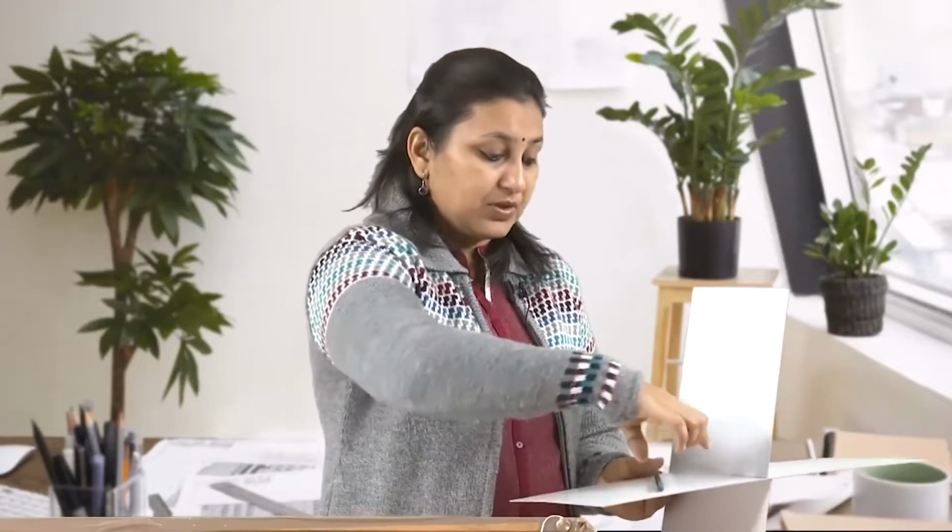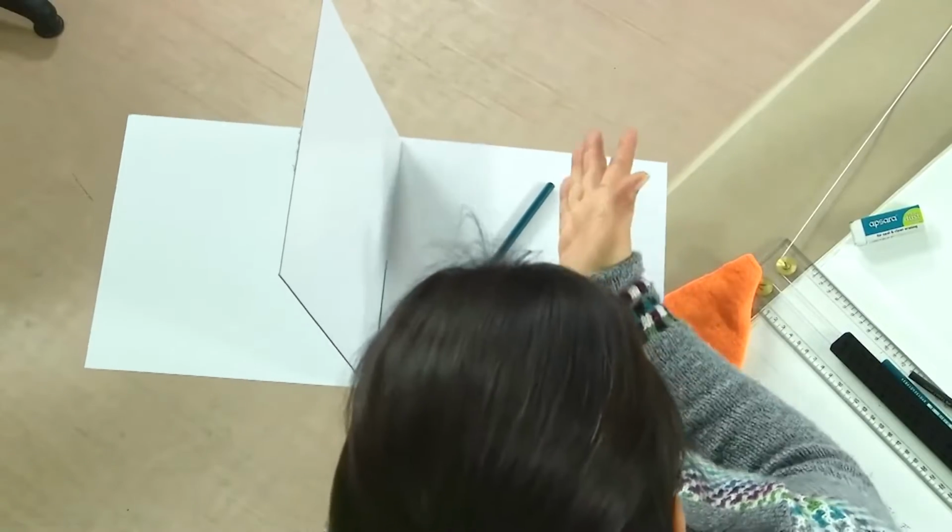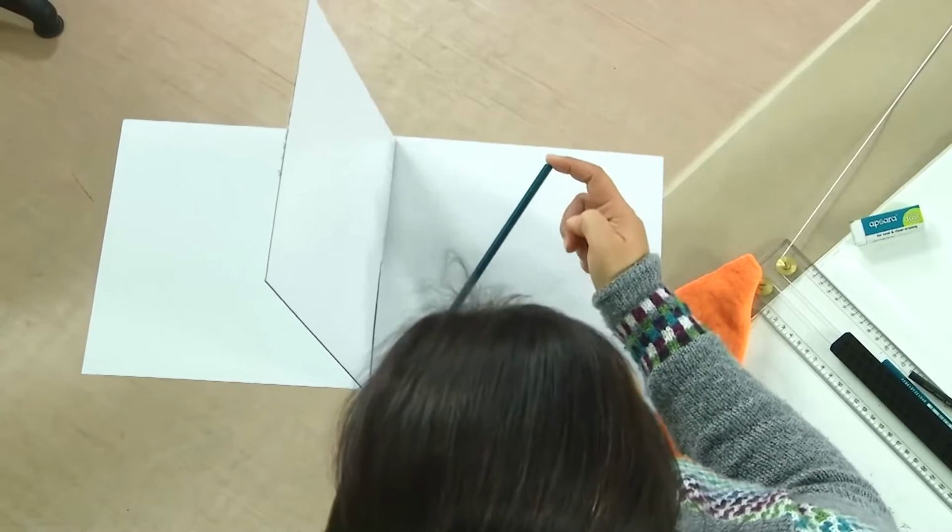We can understand it in the reverse manner as well. Imagine that this line is parallel to HP and it is making an angle of say 30 degrees with VP, which is the final angle. Now, we have to move this line in such a way that it now makes an additional angle of 45 degrees to HP as well. And how do we do that? In that case, we will not move it like this, but we will move it in such a manner that the distance this point has from the XY continues to remain the same. So, we move it like this.